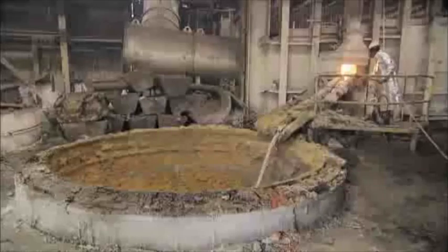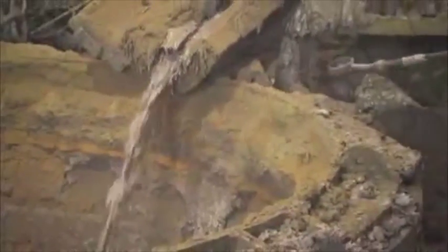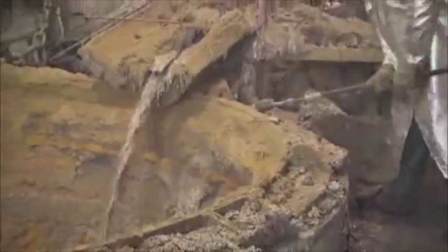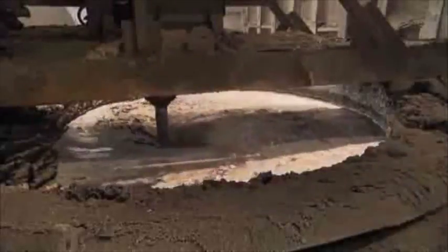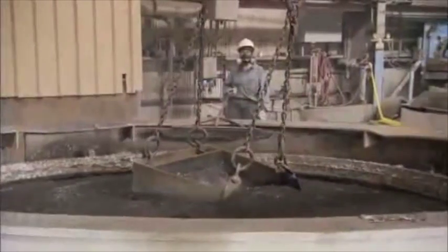These leads still have other metals such as copper, so the top is skimmed off to get copper and copper sulfide out. Then they stir the lead with air blast and skim off the surface to get rid of the arsenic. Silver is removed by doing the Parkes process, which is adding zinc to form a silver-zinc crust at the top and skimming it off.